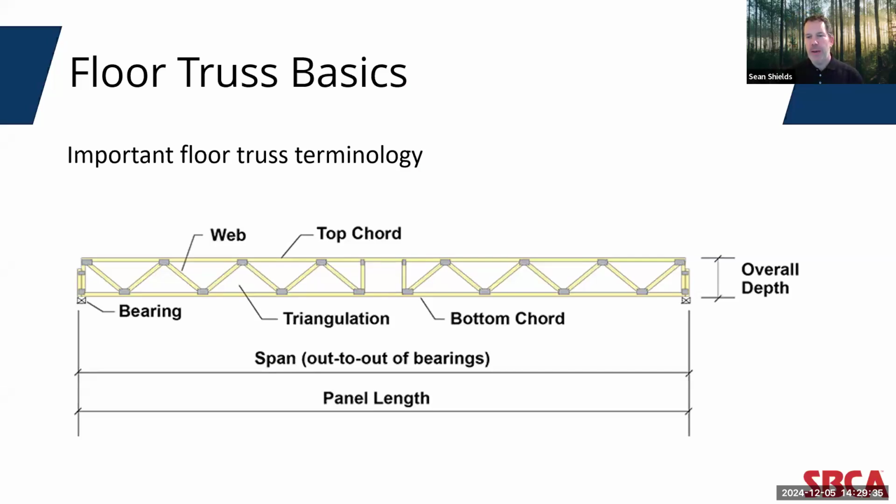So I really just want to share a few observations that impact floor truss designs that come into play in these system details. We're going to be focusing primarily on bearing conditions above and below wall top plates and sill plates. And some of the floor trusses we'll look at in these details will be considered bottom chord bearing trusses. In that configuration, just like the one you see on the screen, the bottom chord typically carries combined tension and bending stresses to the bearing locations underneath the bottom chords.